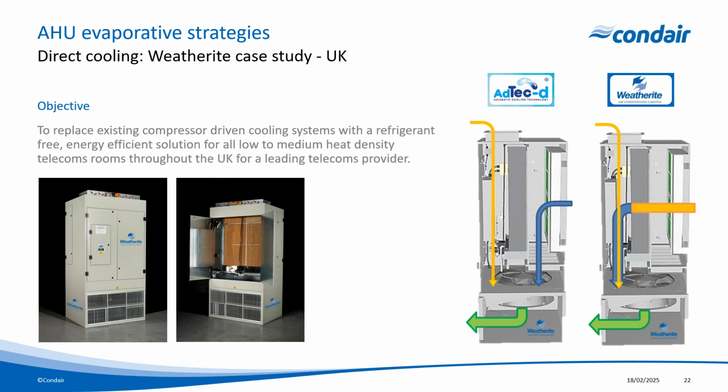So our case study for this strategy is actually from a UK-based AHU manufacturer called Weatherite. The objective here was to replace 30 kilowatt compressor-driven cooling systems with a refrigerant-free, energy-efficient solution for low to medium heat density telecoms rooms for one of the leading telecoms providers throughout the UK. One of the main design requirements was that the footprint for these systems needed to match that of the existing DX cooling systems so they could easily be retrofitted, and they wanted to use direct evaporative cooling.